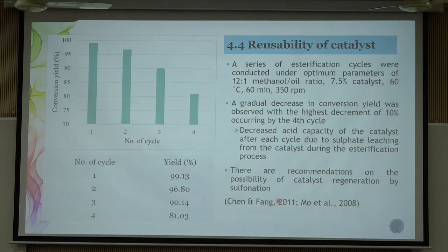So we would recommend, because after the fourth cycle it's reduced by more than 10%, that the catalyst be regenerated through a sulfonation process.